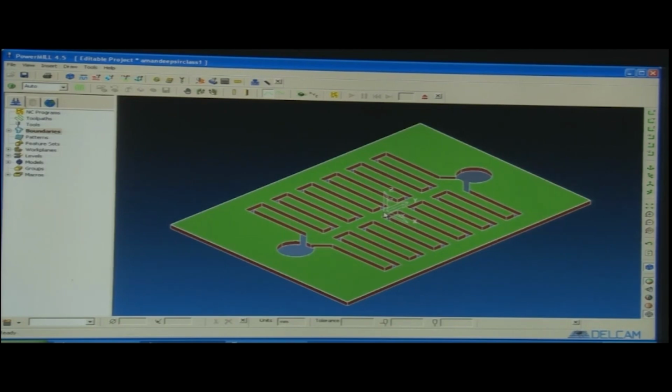With experience, one definitely develops a prowess to work on CNC machines on different kinds of setups. After that, one can sometimes skip some simulation and go directly, but it is recommended to see the simulation or the animation of how the tool runs on the workpiece. So, we need to take care of the coordinates as well. Coordinates can be minus or plus, in the negative or positive direction, but the tool would always do machining in the minus direction here. So, it is very important to note this.